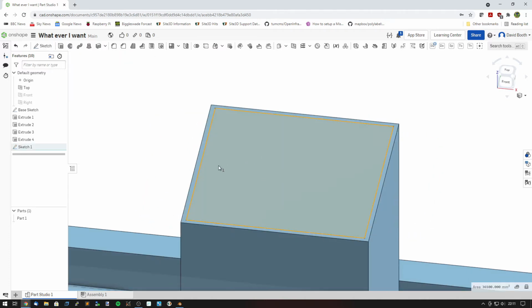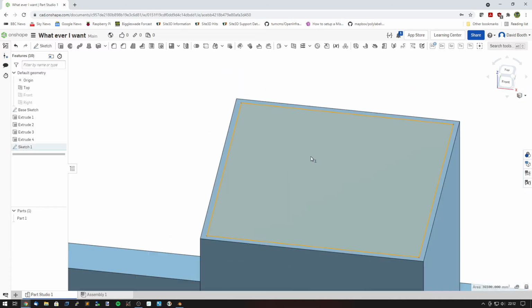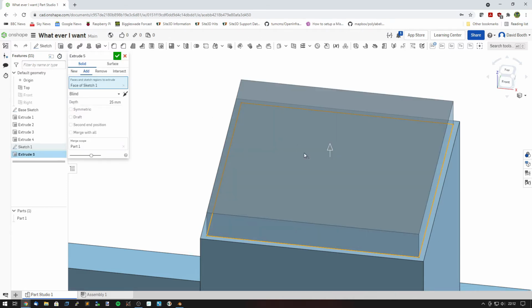Select that face, which is now, because this line that I've drawn on here has split that face, that surface, into two. It's selected, actually, a second, click off. So it has that face and that face. Now I want to drop this one down, so select the middle one and then use the extrude. Now I can then drop that one down.